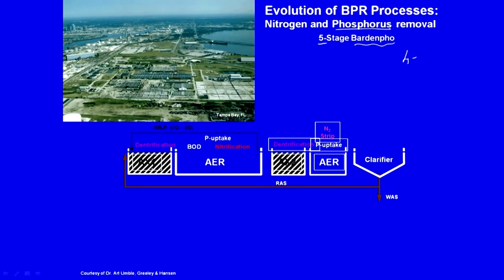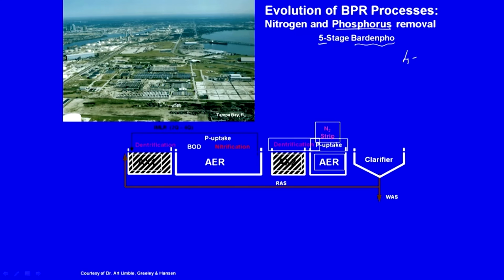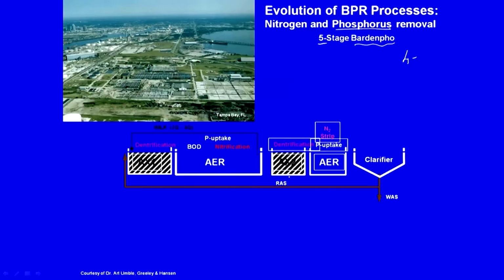We had a denitrification tank before the aeration tank and internal recycle, and then we again had another denitrification tank where it was endogenous respiration, as in the cell mass itself is being used as the source of carbon or the electron donor, and NO3 minus was the electron acceptor. And then you had the aeration to remove your nitrogen from the system. The nitrogen that is given out during the denitrification, you are supplying air to strip the nitrogen from the system here.